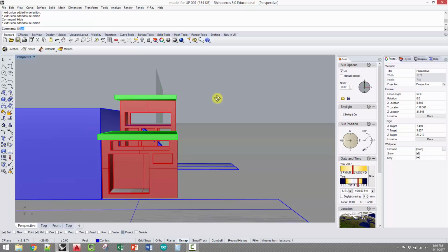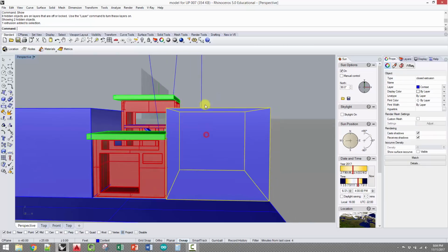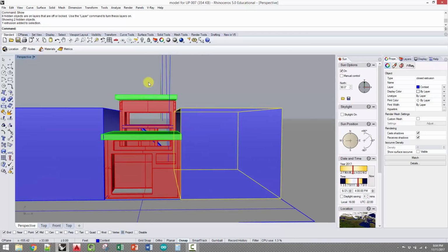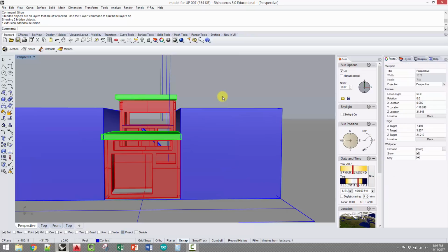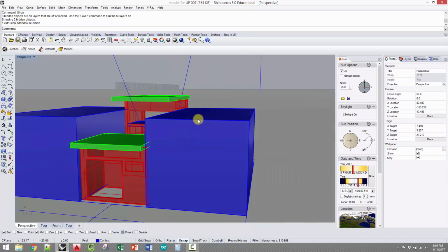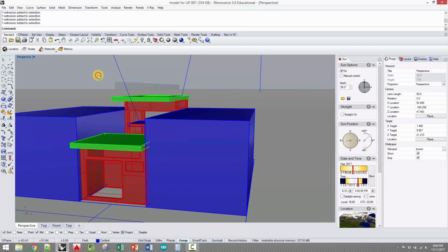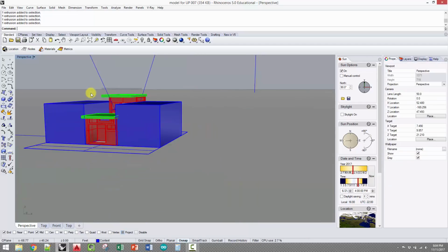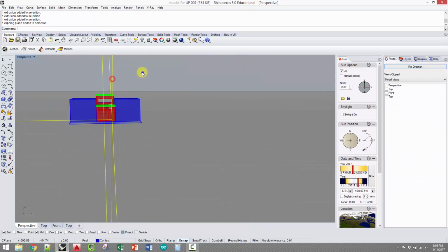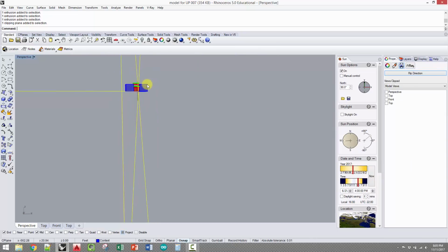And what that's going to allow us to do is actually show the effects of having the neighboring infill buildings within the light. So we have this very narrow space, and it gets very vertical. If we cut the model, then the light would go into it in a way that's not really accurate. So we want to preserve the effect of the infill masses, right? But without actually removing them. And to do that, we have this clipping plane. You can see this kind of 3D thing.